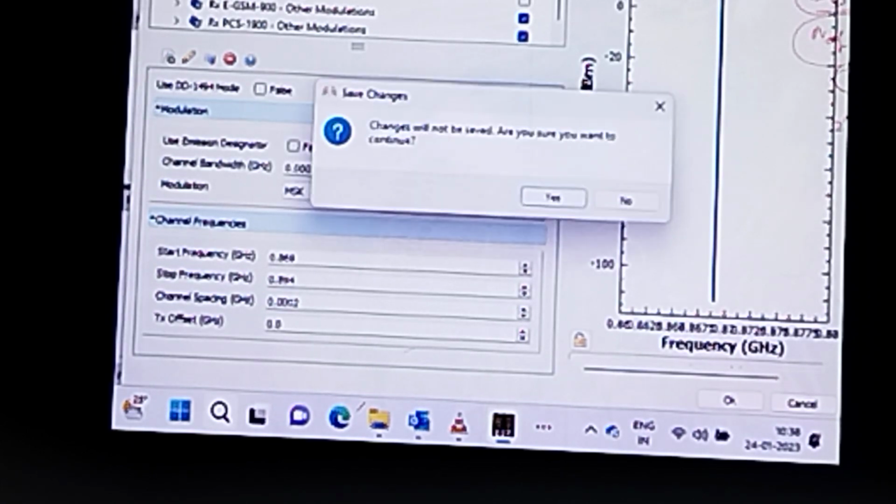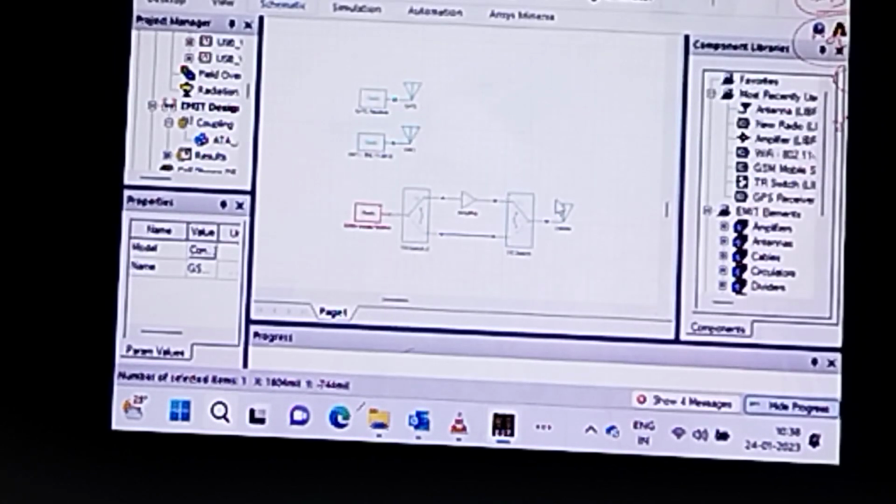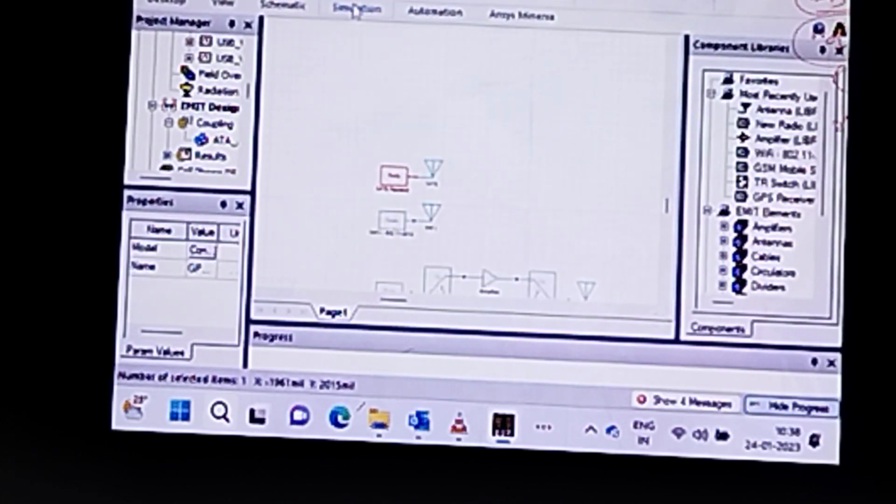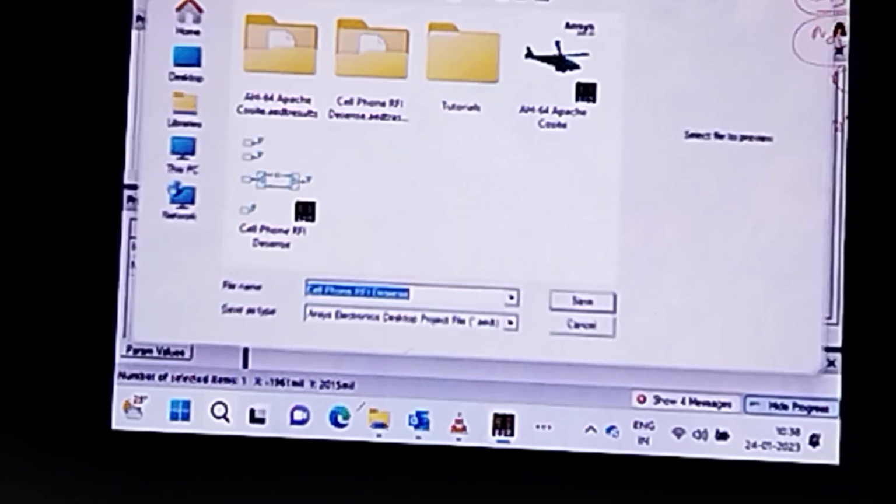So you can see different types of bands here. Basically, you want to incorporate the data of your antennas, and you have to put it here, the far field. Either you can go for far field data, or using the S matrix you can couple it here. Once you have coupled, you need to create an RF system. Then once you have created an RF system, let's just run this simulation and see. Okay, so we'll just analyze this.